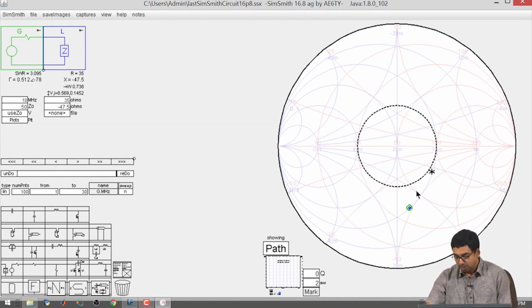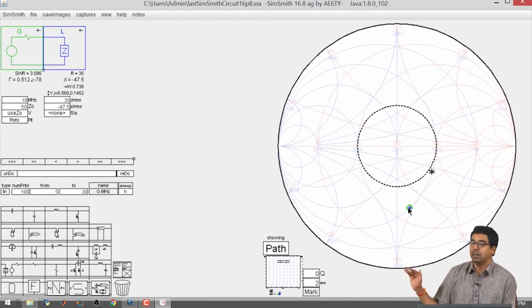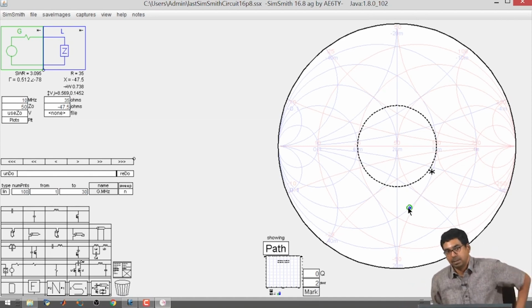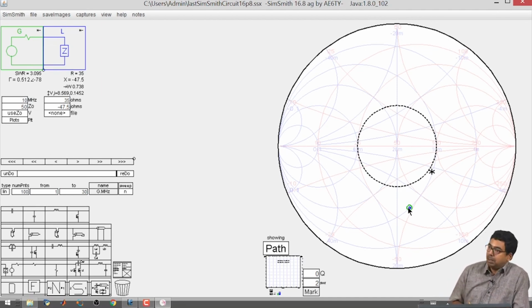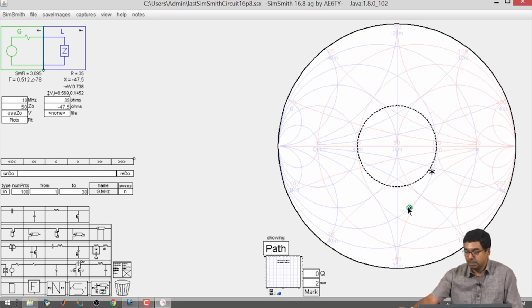Okay. Now, the load impedance is not on the horizontal axis. That means that it is clear that you have to do some reactance manipulation also. You will need to add some passive components, and you will have to add some reactive components. The resistor will get you along the circle, but you will still need to get here. Going up here needs some L and C.